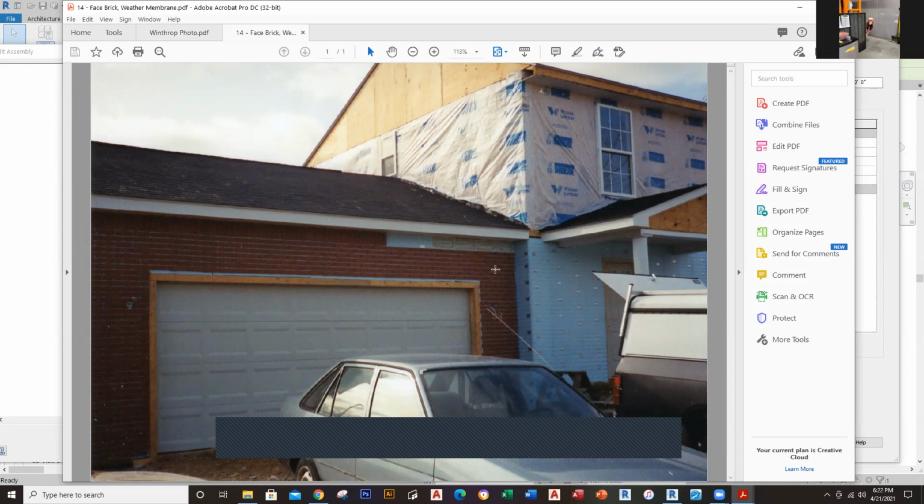Okay, what you got right there is the face brick that we use. You can see it's like a 3/4 inch brick veneer, and then you have a blue styrofoam product with clips, and the bricks snap into those. They act like a mechanical bond, and that's what holds it together. When it was all done, I used a cake decorating bag full of grout and grouted all of the joints. Took a long time.